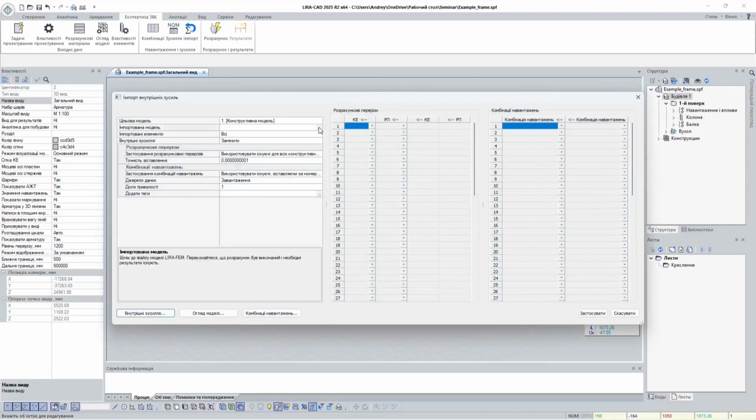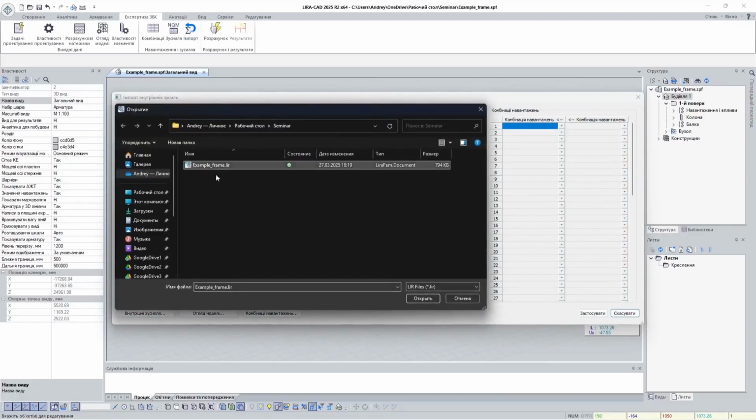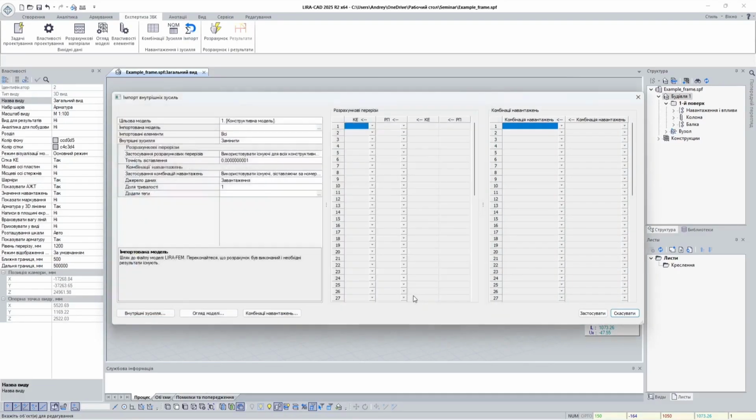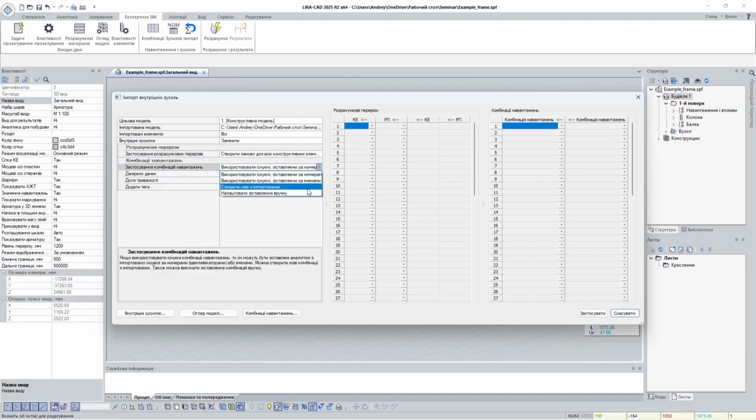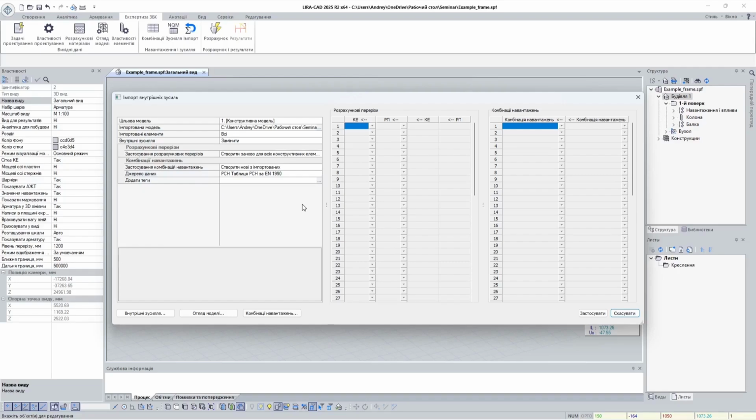Does it show you what's being imported? Oh, yes. There's an import dialog that clearly shows you the mapping, section IDs, load combination IDs, the status. You can even make manual adjustments if needed. Good. And once they're imported, you can view the forces and the combinations in their own dialog windows. And, crucially... Let me guess. Tags. You know it. You assign the necessary tags to the imported load combinations to link them to your calculation tasks as well. Okay, makes sense.